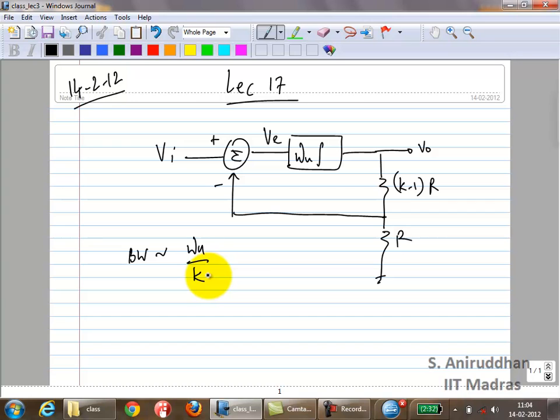We put in a sinusoid, looked at what happens when the linear phase approximation is valid, correct? And we found this was the condition, that the frequency needs to be less than, actually much less than omega u over k, but we say up to omega u over k, it's a pretty good amplifier. Not the best one, close to omega u, but it's pretty decent.